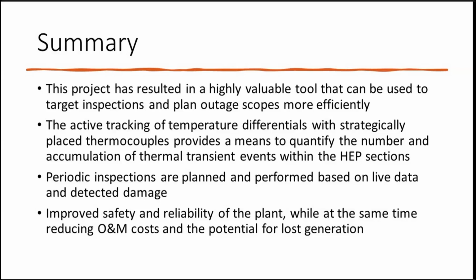Plus, since a lot of this is on P91 material, now you're stuck with post-weld heat treating, and the cost would probably go up by 10 times to get involved in that. Great point. Yep.